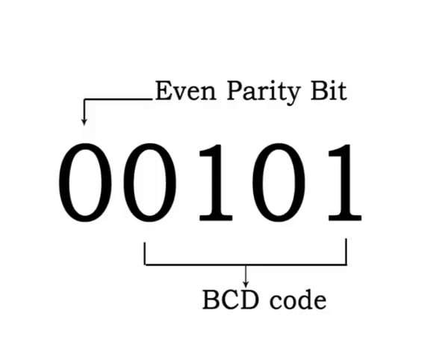Detecting an error. A parity bit provides for the detection of a single bit error or any odd number of errors, which is very unlikely, but cannot check for two errors in one group. For instance, let us assume that we wish to transmit the BCD code 0101. The total code transmitted, including the even parity bit, is 00101, which consists of the BCD code and the even parity bit as shown.